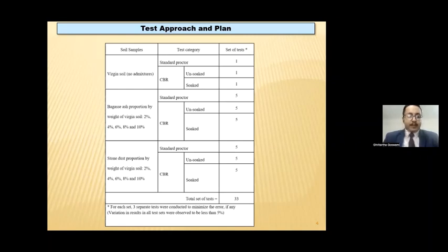Previous studies also revealed that the optimization of compaction and penetration characteristics was achieved when the quantities vary between 4 to 12% of the weight of dry soil. In order to ensure adequate enhancement of the compaction and penetration characteristics of the treated soil, while limiting the transport cost to ensure cost effectiveness, the maximum quantity of admixtures has been restricted to 10% in the study.